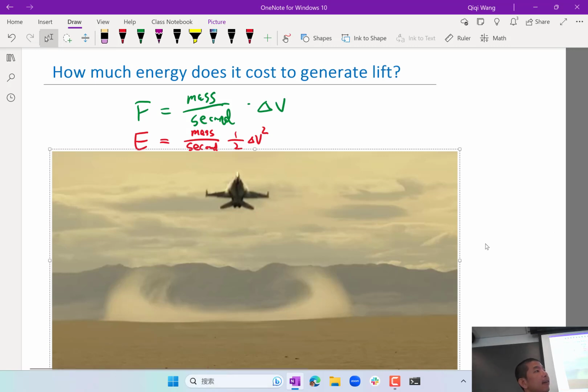So if you want to move more mass, you would want to increase the velocity of the plane. Yes, another way to increase the mass per second is to increase the velocity of the airplane, right? That is why for a slow-moving airplane like a glider, you really want to have a very large span. For a faster-moving airplane, it's less important. All right, so very good point.